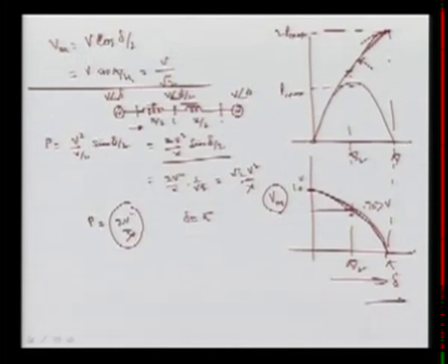Now you can see there was some stability problem here, meaning it was not possible to load the system more than this 90 degree angle, that is pi by 2. Even below this we never load fully, because some surge or transient will lead the system into the unstable zone. So in steady state we can go maximum up to this point. Now we can go to twice that, and here all the region is stable, whereas earlier it was not stable beyond this. So we have increased the steady state power transfer limit of the system to twice the P max value.